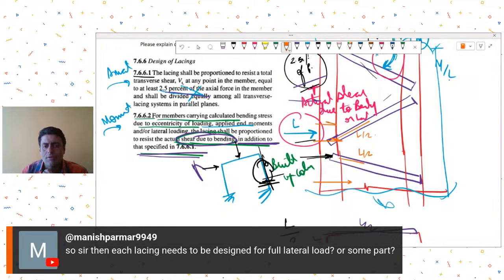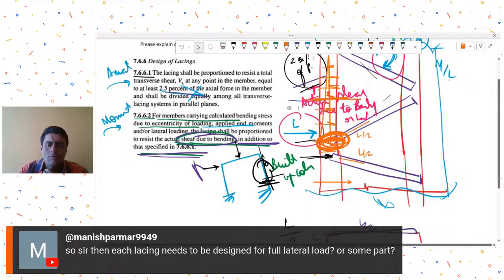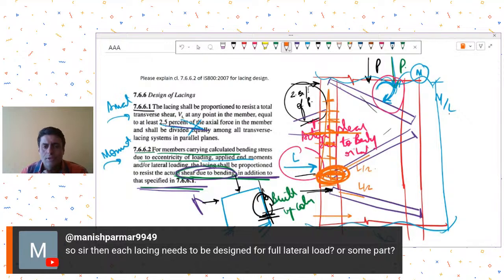That is one. If you have some shear force, you will need to convert it into the load that gets transferred to this point by some tributary width calculation. So if you have the shear over this length, you multiply that shear force, or you find the equivalent point load acting on this.